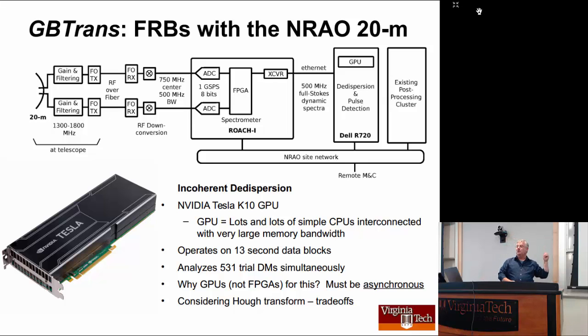With FPGAs, that's what we use for FFTs, that's what we use for FIR filter banks, things which can be utterly synchronous, FPGAs are great. But for dedispersion, when you want to take the same data set and dedisperse it 100 different ways, well, sure, you could do that in an FPGA, but you'd spend your time trying to figure out how to synchronize all these operations. See, all the dedispersions don't operate at the same time or with the same number of operations.